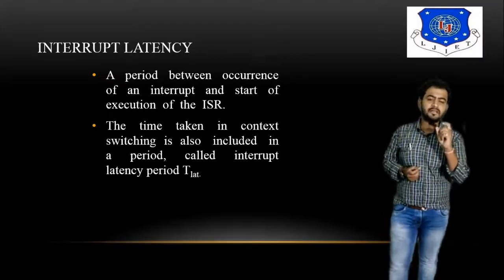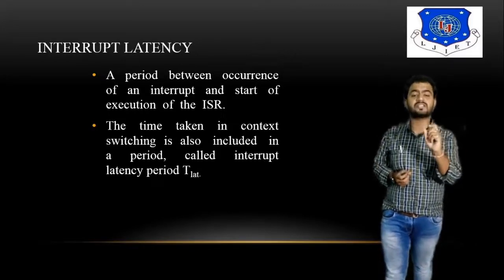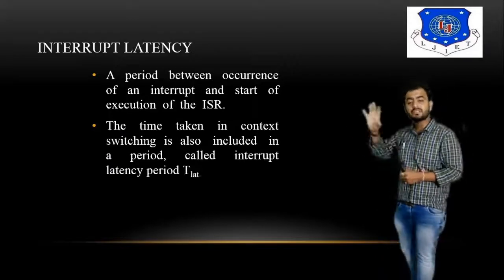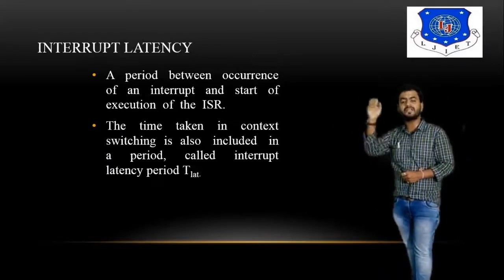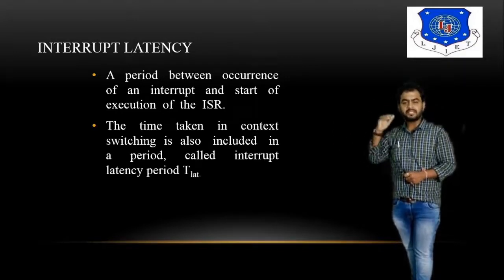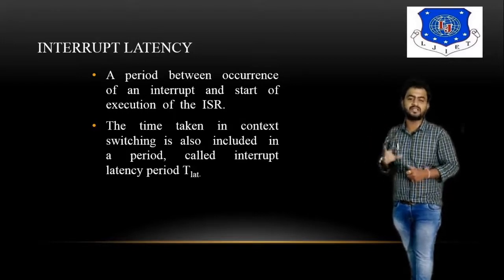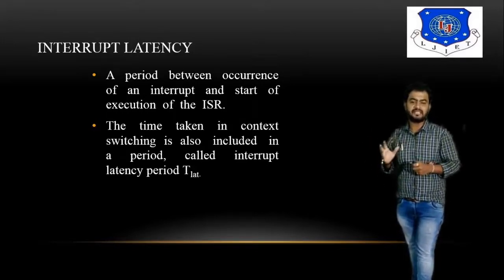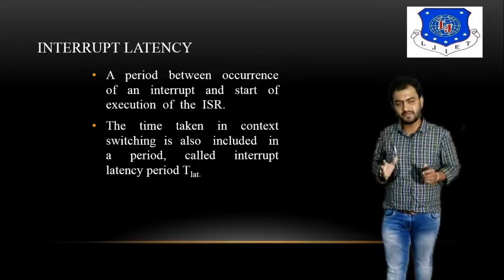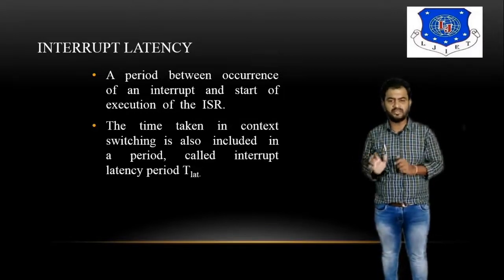Latency means that we are talking about the execution of a task in a particular time manner, so it is called latency. Here we discuss the time period between the occurrence of the interrupt and the start of execution of the interrupt service routine. The time taken in context switching is also included in this period. It is called the interrupt latency period, T_LAT. In terms of latency, we have to focus on the execution of the task with respect to time only.